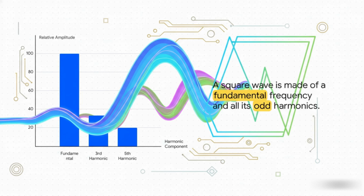Now this is what's so cool about it. When we run our ugly square wave through this process, we get its unique harmonic fingerprint. And this chart shows us exactly what's inside. You see that first really tall bar? That's the main frequency we actually want, our fundamental, let's say 60 Hertz. But look what else is in there. There's a big chunk of the third harmonic, which is a sine wave at 3 times the frequency, 180 Hertz. And then there's the fifth harmonic at 300 Hertz, the seventh at 420 Hertz, and on and on. It turns out that a perfect square wave is mathematically built from the fundamental plus all the odd-numbered harmonics, with their size getting smaller as the frequency goes up.